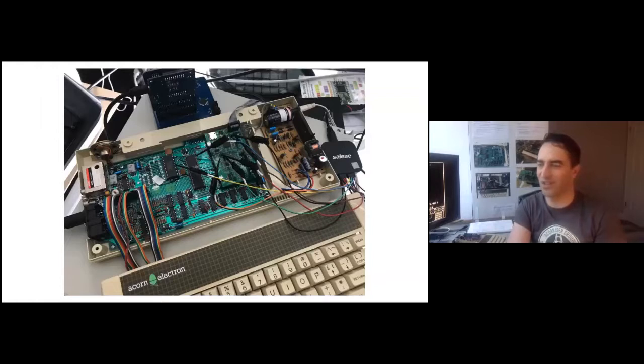I think I could see something using Hoglet's 6502 decoder at this point. But it was not making it very far into the boot process. It was reading something out of the ROM. So yay, ROM input was working, address and data bus were working fine. Clock was working, but it turned out that the ULA is supposed to pull up the NMI and the IRQ pins on the 6502, and mine wasn't. You can't see it on here, I guess this photo was taken before I figured this bug out. There's a couple of through-hole resistors soldered on top of the now working one.